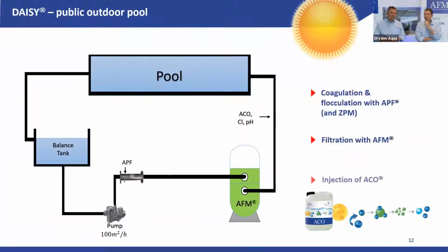Let's start first with outdoor pools. In outdoor pools, you will never have a problem with combined chlorine. Never. Why? Well, it's that sun up there. The sun is the biggest UV lamp you can get. You can't get it bigger. That's a really powerful UV unit, which will create free radicals in the pools and will oxidize the combined chlorine, inorganic or organic, doesn't matter.